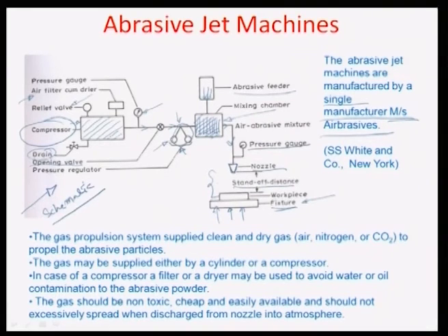In the microsystems fabrication case, the only other useful component is a mask, which is like an open mask. This open mask is used for guiding the abrasive particles onto the surface, thus creating certain features and structures on the surface. They are like small wells, and the remaining area of the mask is pretty hard, so it is not amenable to much wear, and the particles which strike it are the particles which do not do any machining.